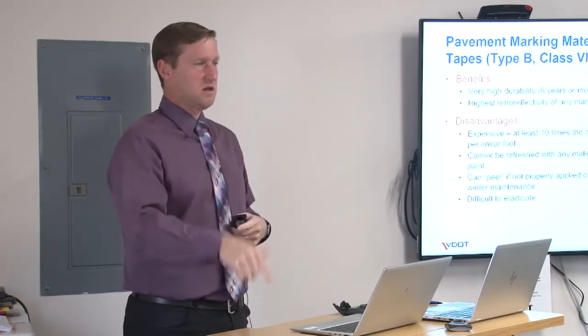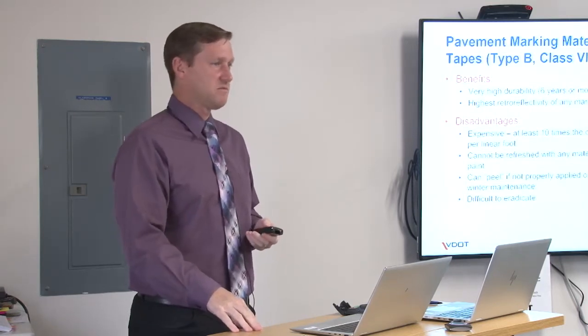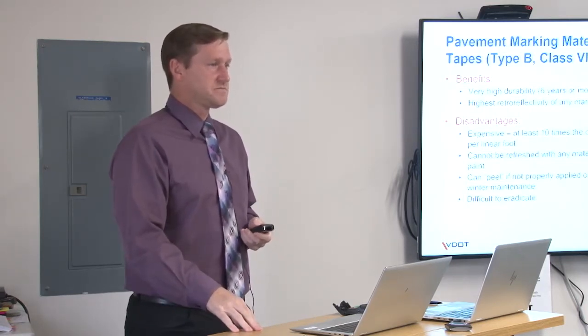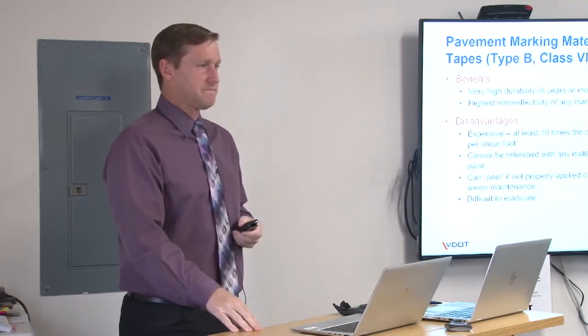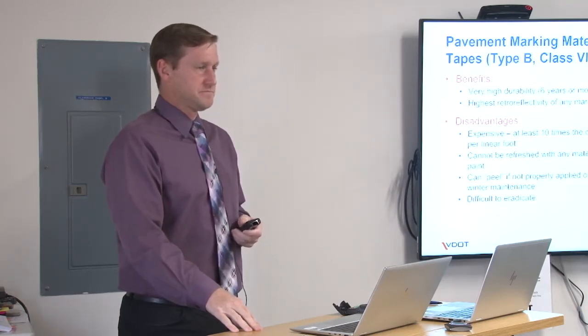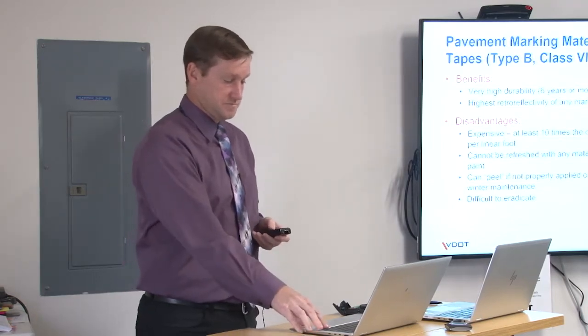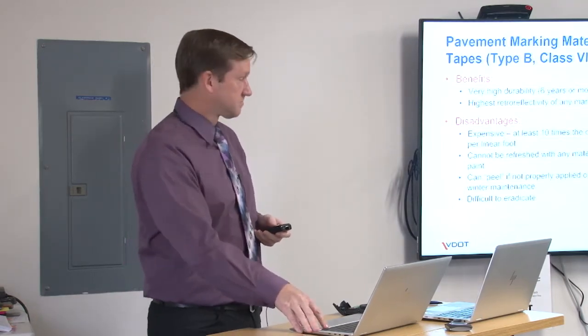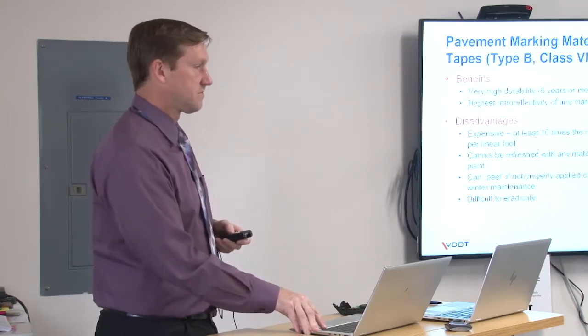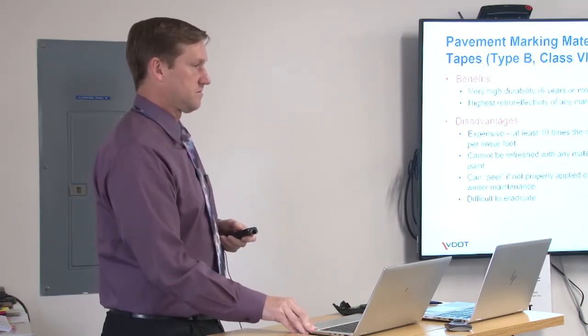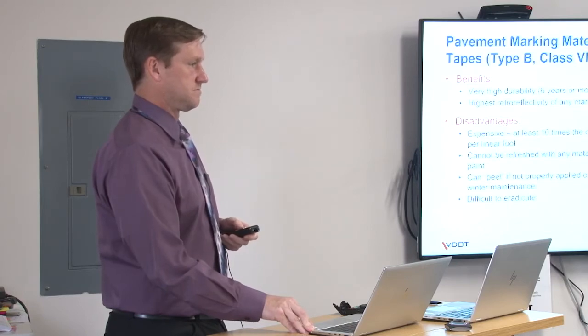to increase that longevity of the marking. Yeah, but only for like 6 months. Right. I mean, like say on V6 tape, the only option you have is come back with latex. Right. Pretty much any other marking can be put on top of itself, except for V6. Mm-hmm. That looks so bad though, that refresher paint. Yeah. Never the same width, it's always not the same shape even.